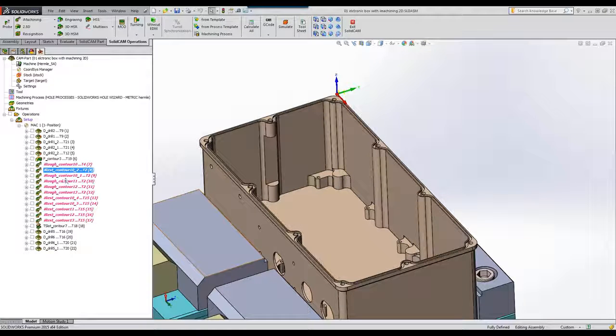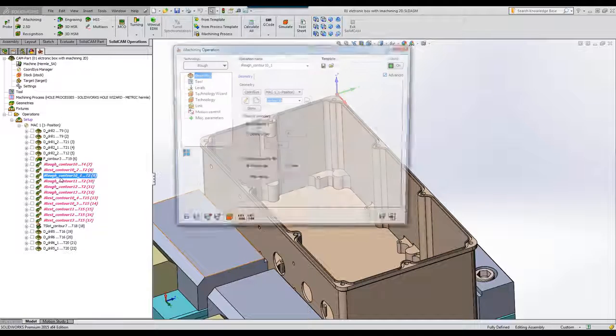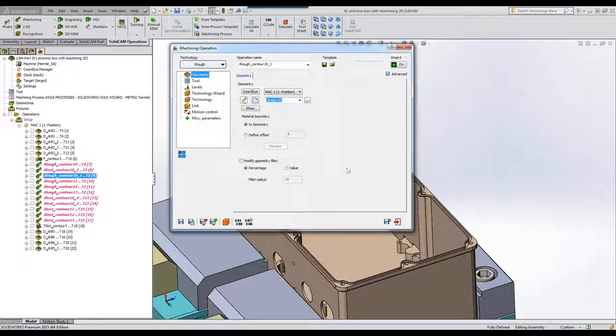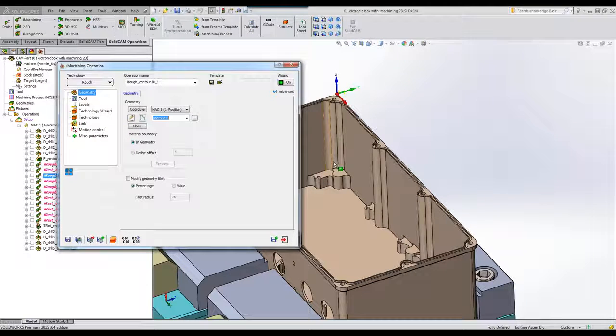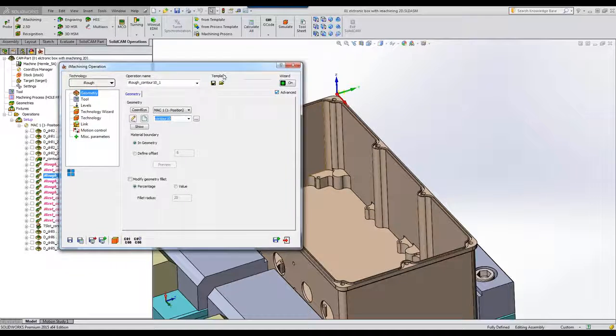Now, I used the same geometry, but this time I had a smaller tool, but this tool actually was made specifically so that I can go down deep. I don't want to take heavy cuts with this because it is sticking out a large amount. So I took that really deep, heavy cut as much as I can up until that area, up until 80 millimeters as much as I could.